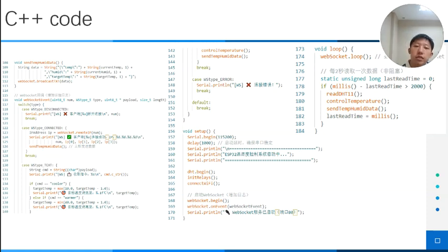The other is the sensor data collection module, which initializes the sensor and encodes the reading function to obtain data through the DHT11 driver library, and at the same time handles abnormal situations where sensor reading fails to ensure the stable operation of the system.